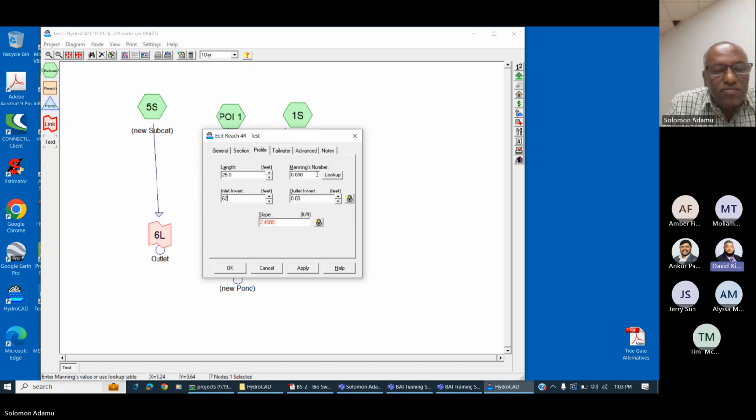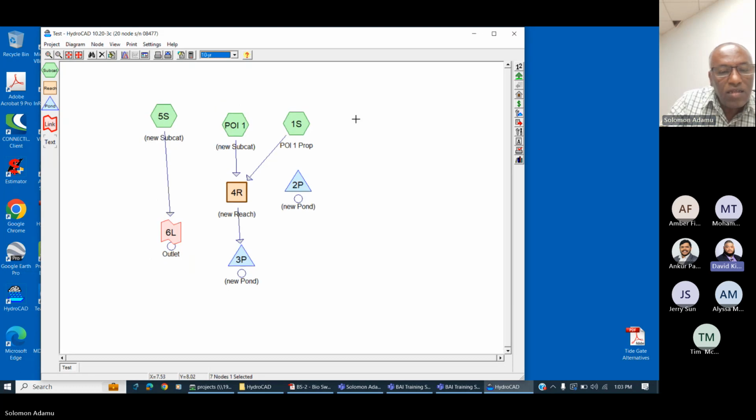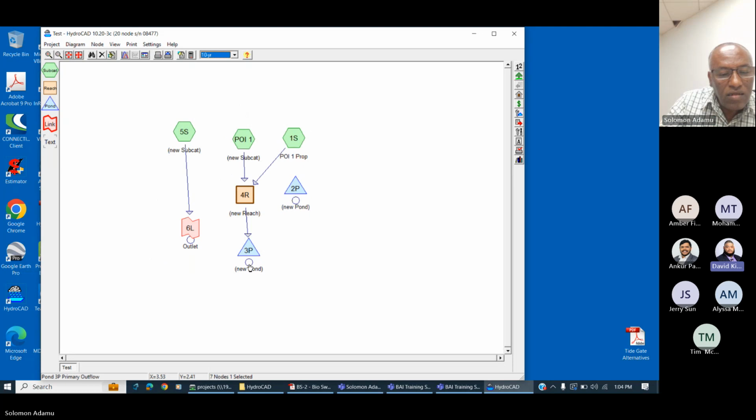Let's say, for example, it's a little bit complicated, but what if you have one pond, the pipe goes to one pond, and that outfall is a rectangular weir, and right after that rectangular weir is another pond or a micro retention? Are you talking about something like this? A pond outfalling to another pond? Then you're going to create a tailwater effect, because this pond creates a tailwater condition for this one, and that means it's going to affect the discharge here.